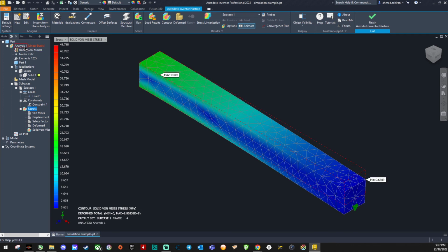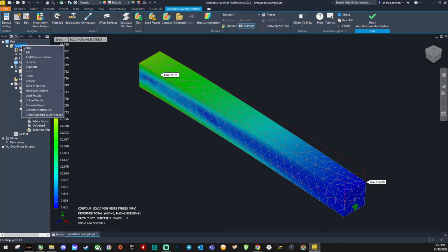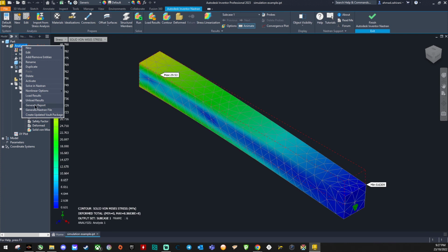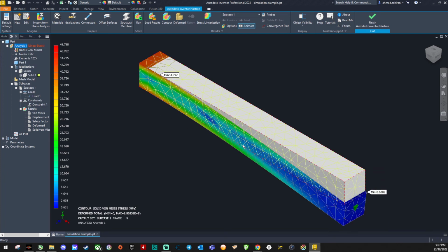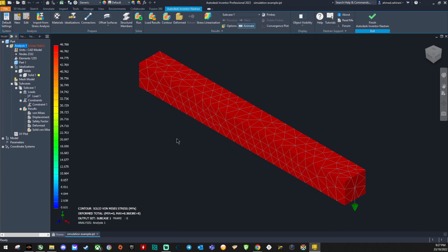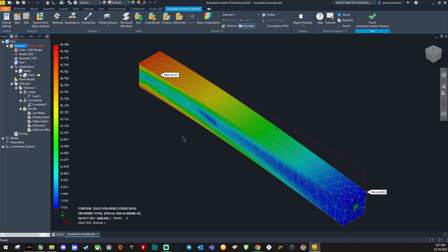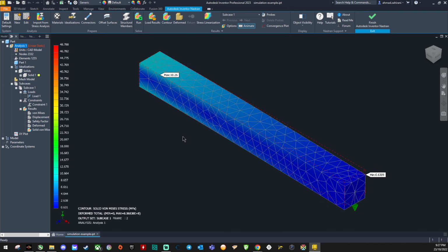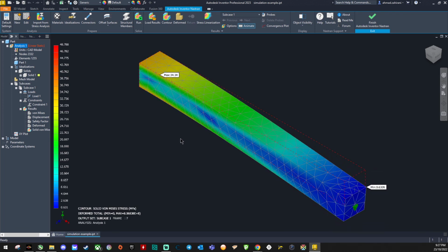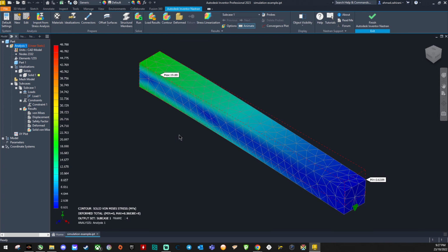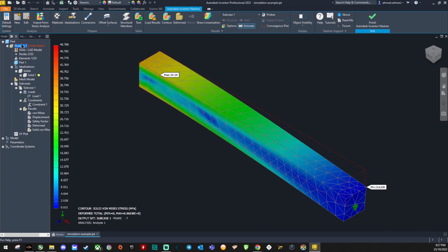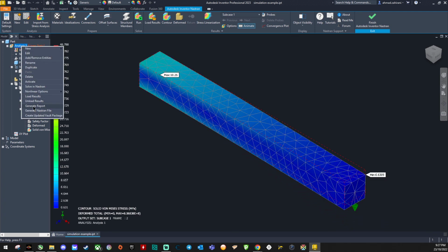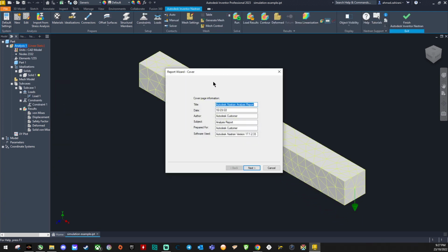And then right click on the analysis, and from here you can select the option generate report and select OK or select yes. Give the software a few minutes to generate the report. Okay, do it again if the report doesn't appear.